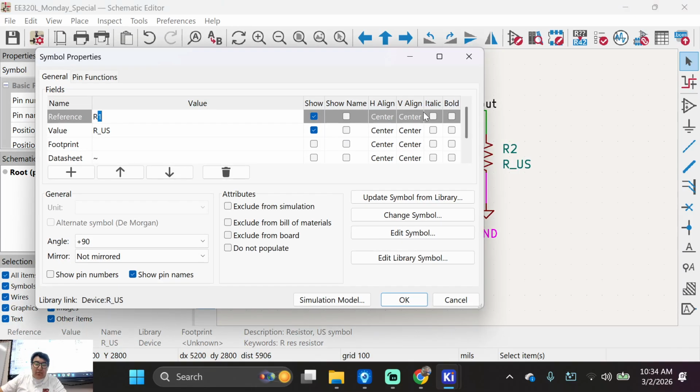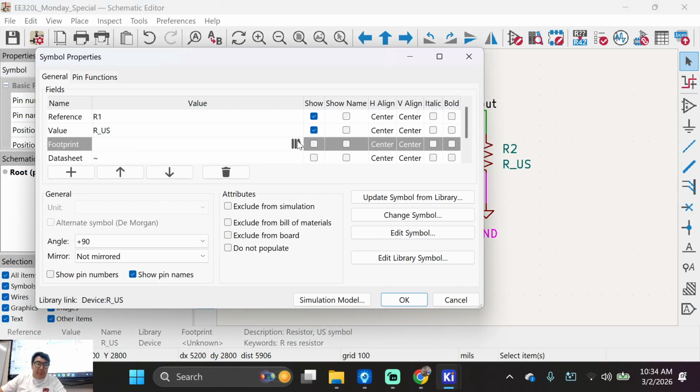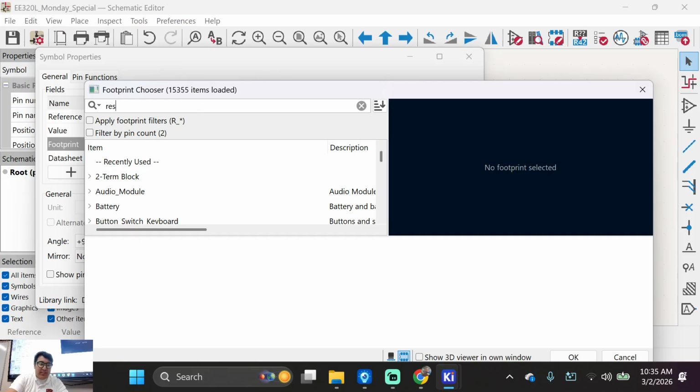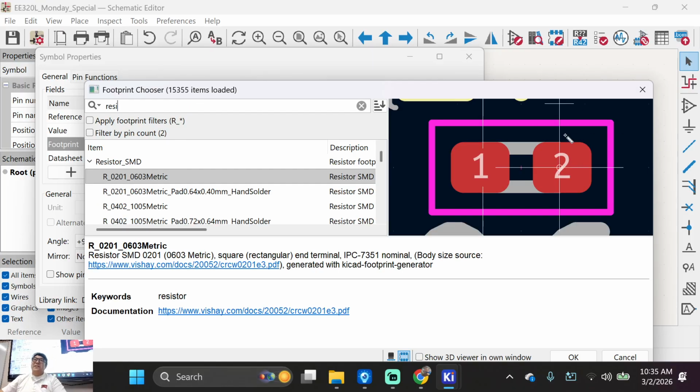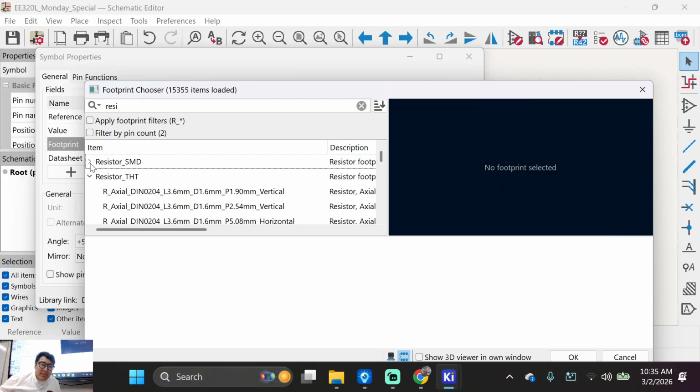So I'm going to double click on the resistor, click on footprint, and click on this book right here, the libraries. Let's go to resistor. These are called SMDs, surface mount devices. These are the pins that you see. They don't go through a board. It's just paste, and you have to find the component. These are tiny, smaller than half a grain of rice. You can use that. I think we have a few of those components, but I'd rather everyone solder like professionals with actual soldering irons. So don't use this library here.